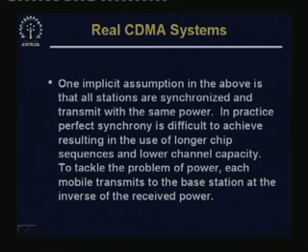One implicit assumption in the above is that all stations are synchronized and transmit with the same power. In practice, perfect synchrony is difficult to achieve, resulting in the use of longer chip sequences and lower channel capacity. Secondly, to tackle the problem of power, each mobile transmits to the base station at the inverse of the received power. So, there are practical limitations, although this looks very nice. The theoretical maximum that we could achieve, we get less than that, but even then this is an elegant system.